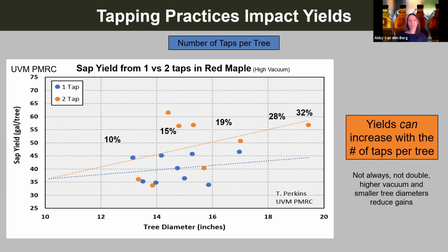And then also from Stu, Maple News carried an editorial column recommending cleaning 3/16 line with swimming pool bleach, calcium chloride, and leaving in lines till fall before hot water rinsing. Do you concur? Well, yes, we actually have it. Unfortunately, that swimming pool cleaner actually also is this Zapit calcium chloride bleach. I'm sorry, not calcium chloride, calcium hypochlorite bleach. That is also a potable water sanitizer. So even though that particular product can be used for swimming pools, it is also food grade. So that part is okay.